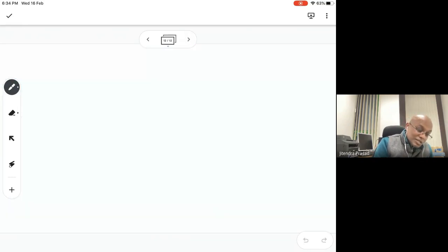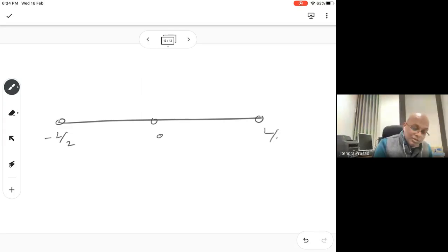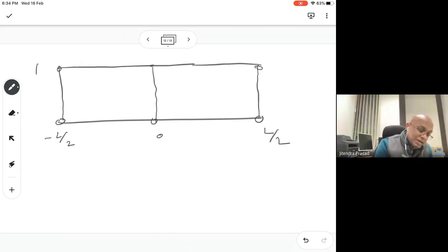You can actually plot it. Here you have 3 nodes: minus L over 2, 0, L over 2. From here to here is 1. Let us say we plot number 1, N1: it is 1 here, 0 here, 0 here, and this is quadratic, meaning it will have only one bending basically, right? So it has to go here and go here.